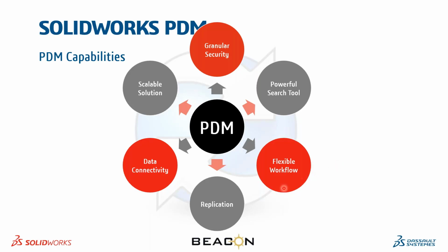It could be anything. Next is replication. Replication is a feature in PDM that allows you to share data instantaneously with anyone within the organization, no matter where they are in the globe. So if you have multiple sites in your organization, like you're working with different teams sitting in different locations, you can have replication set for them in the server, and as soon as you upload the file here, it will be made available for them over there as well. Or even if they upload there, it will be made available to you here sitting in your office.